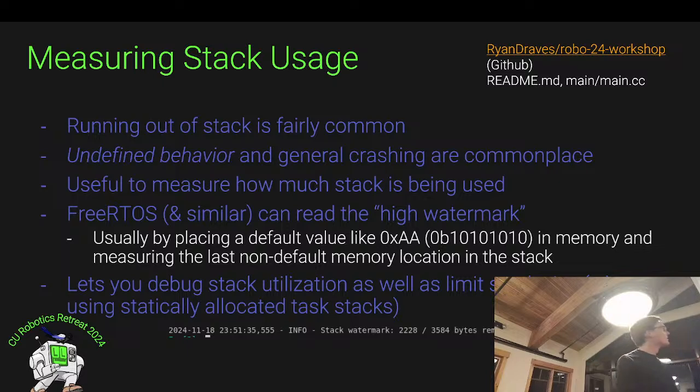As we can see here, I measured the stack usage, and a little more than a kilobyte was used, and 2.2 kilobytes were left. Plenty of stack to do more complicated things with this device than just read out the sensor. It's not optimized at all, but not too bad at all.